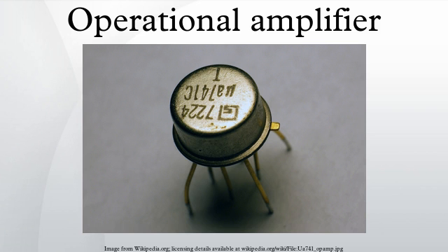Input offset voltage. This voltage, which is what is required across the op-amp's input terminals to drive the output voltage to zero, is related to the mismatches in input bias current. In the perfect amplifier, there would be no input offset voltage. However, it exists in actual op-amps because of imperfections in the differential amplifier that constitutes the input stage of the vast majority of these devices.